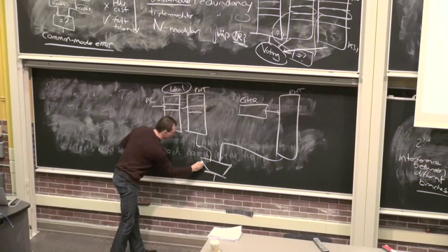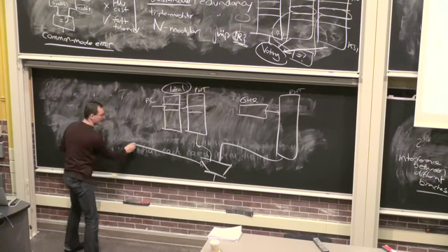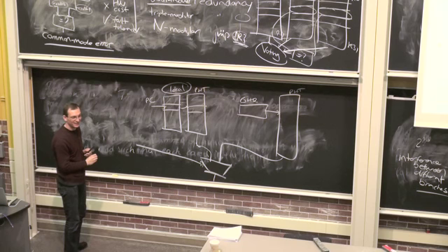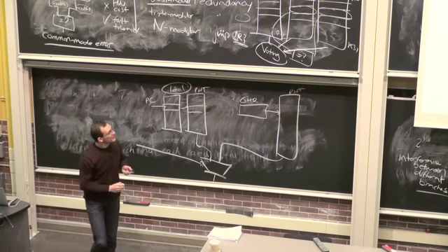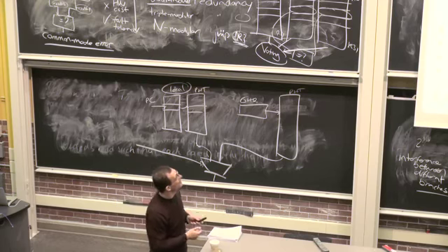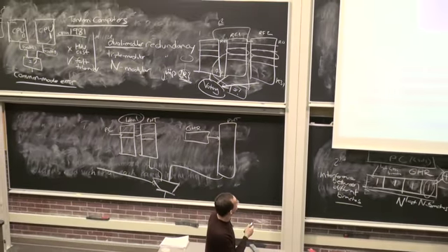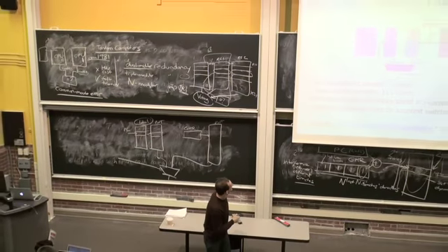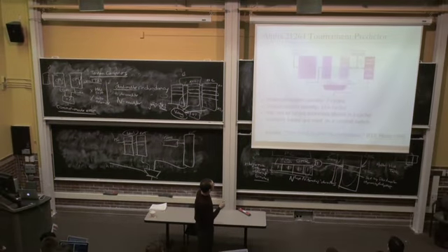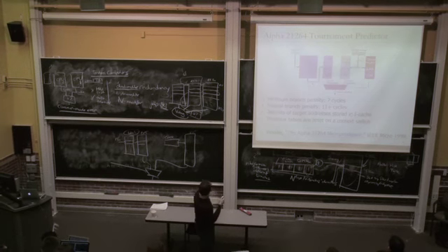So how do you pick the one that makes sense? Well, how do you design this control of this mux? Well, I'll show you one example, I think. This is the Alpha 21264, which was one of the fastest machines of its time. And existing machines use similar tables like this. But actually, this is essentially the same thing I showed you here. You get a local prediction, and you get a global prediction. And you choose between them using something called a choice predictor.